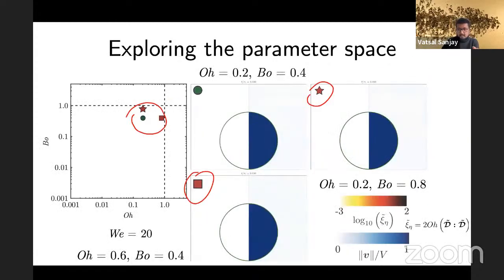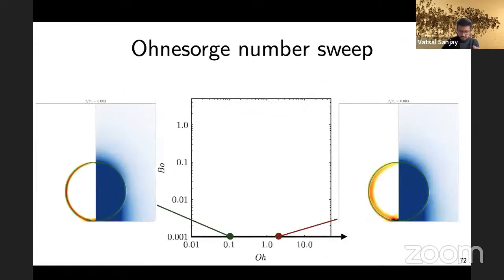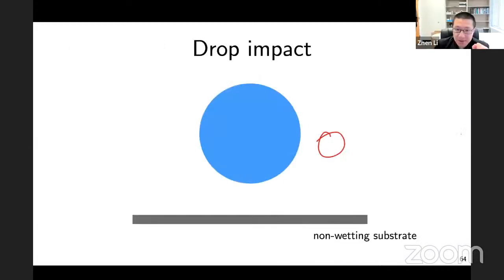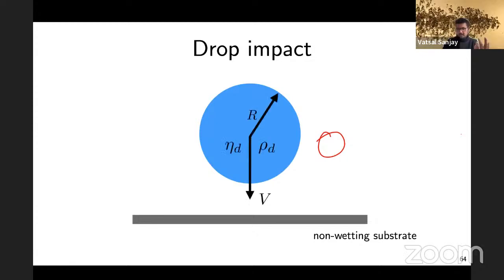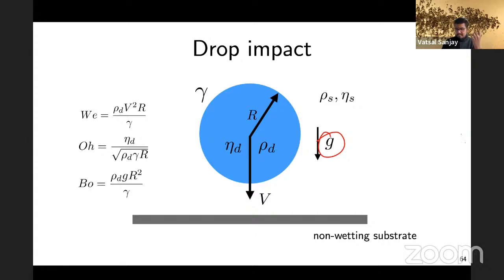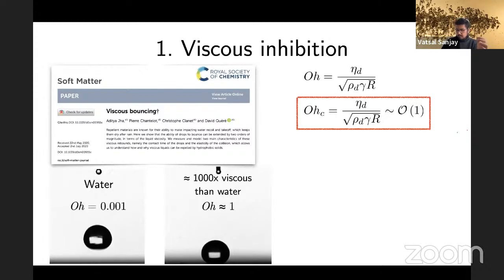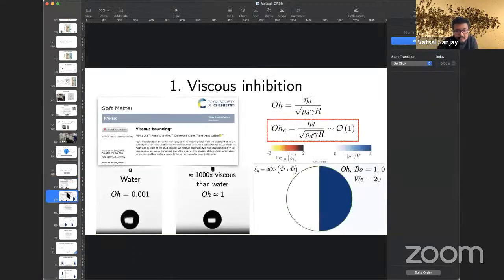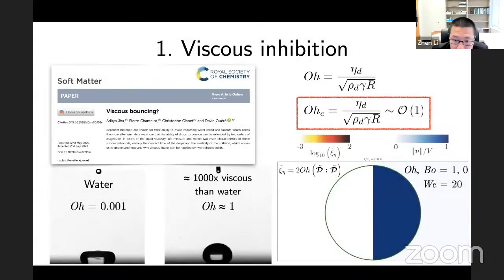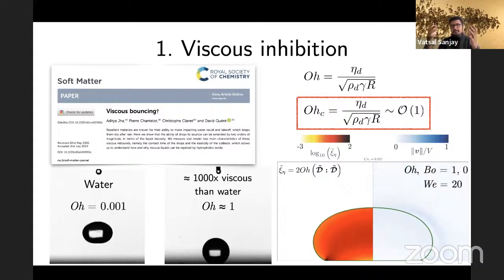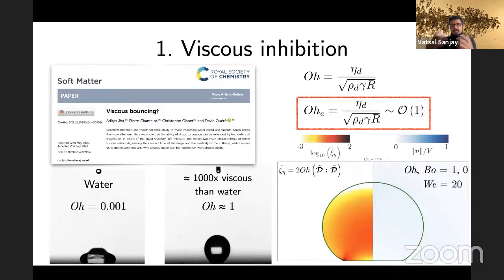Oh, okay, so that's way back. Let me see. First of all, it cannot be a pinning effect, because in the simulations we don't have a contact line. We assume there is a thin air layer, of the same order of magnitude as the grid cell, that is always present between the droplet and the surface. So you said slide 67? Yes. Then we have this thin air layer between the drop and the surface, which means there cannot be any pinning.